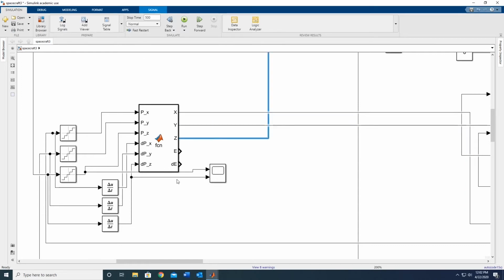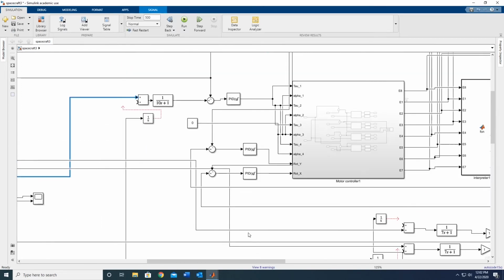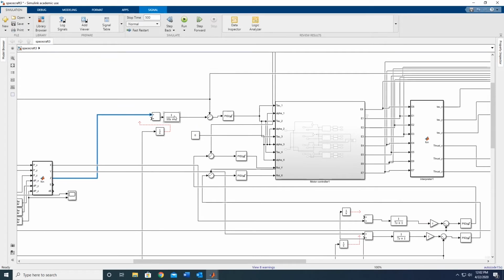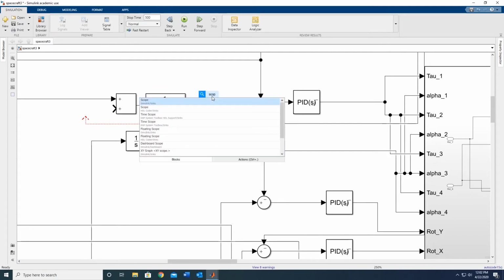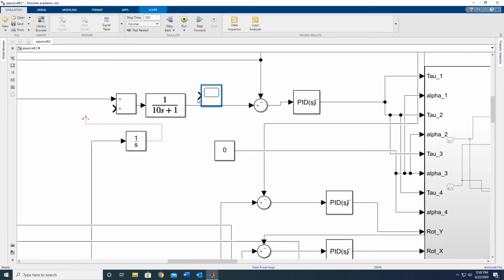Okay. Once the signal comes out on those rails, I feed it in through a set of time delays. This is so I don't error shock the system. So when I update to the new set point, there's a time delay associated with it. So if I go ahead and say step plot this function, let's go ahead and just step plot it. Look it up there.